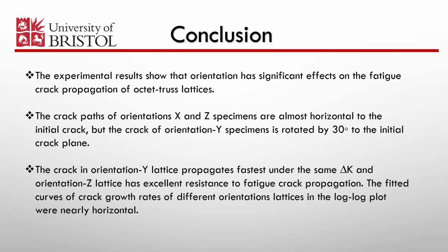Here are the conclusions. The orientation effects on the fatigue properties, including crack propagation rates, of octet-truss lattices are studied in the present research. The experimental results show that the orientation has significant effects on the fatigue crack paths. The crack paths of orientations X and Z specimens are almost horizontal to the initial crack, but the crack in orientation Y specimens is rotated by 30 degrees to the initial crack plane.